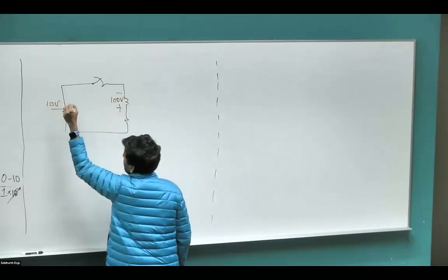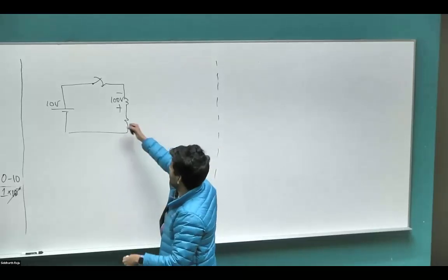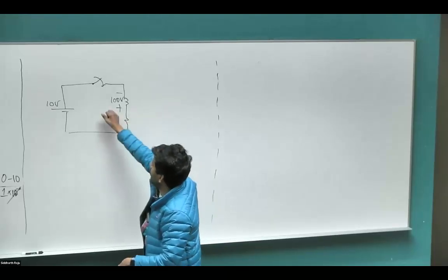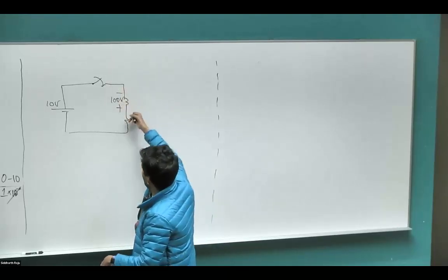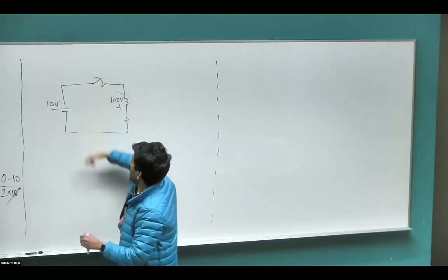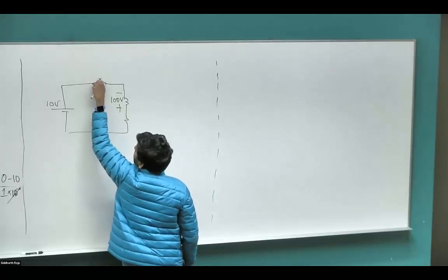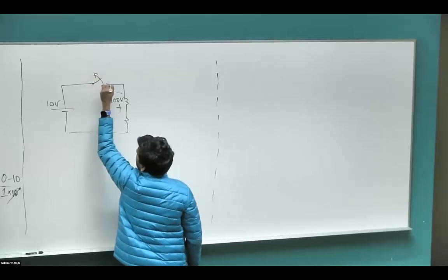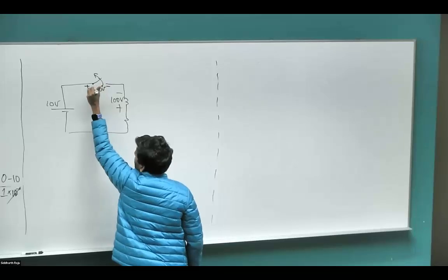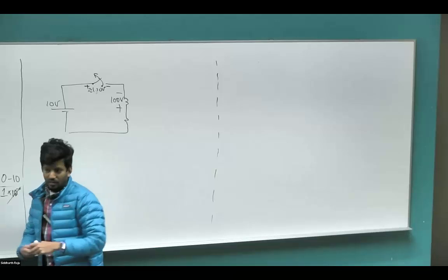And then we have 10 volts across this. Let's assume the voltage across the resistor is negligible. It's going to be a maximum of 10 volts, negligible compared to the voltage drop across the inductor that we are seeing. So this is going to put a huge voltage across this, plus whatever little resistor drop is subtracting out, plus the source voltage is all going to appear across the switch that just was opened. So we are going to have a net voltage of about 110 volts, give or take, across the switch. And this is going to cause arcing in our switch.